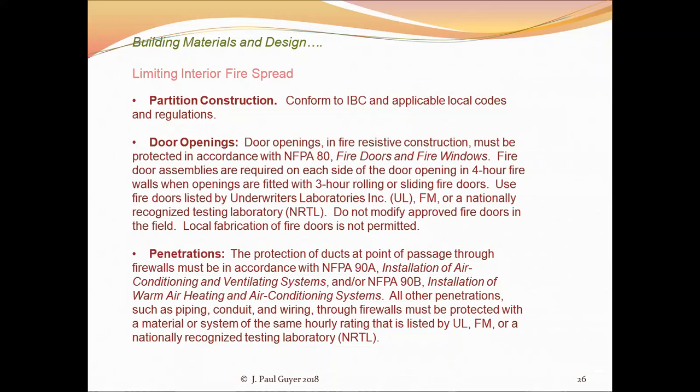So in the event of a fire, it might be a fusible link damper, fusible link melts, damper drops, and the damper has a 2 hour fire resistive construction, which prevents the spread of flame and also smoke from one area to another. And also there are electronic releases on fire doors as well, rather than fusible link.